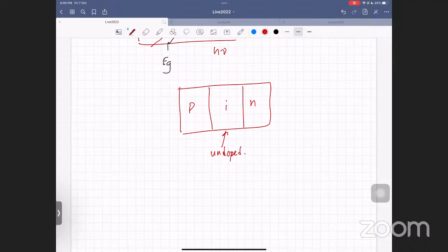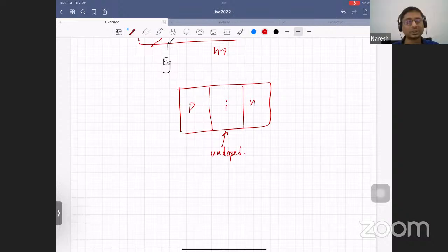Sir, Kushagra again asked a question. Why do we study HFCV and LFCV? Because it tells me about how the inversion layer behaves. How does the inversion charge respond? Because finally, if you want to switch transistors on and off, what matters? The minority carrier lifetimes. If I study at different voltages, I can see, I think I mentioned this also, MOSFET CV is used as a diagnostic device. Just by looking at the shape of the CV, we can infer a lot about the physics.